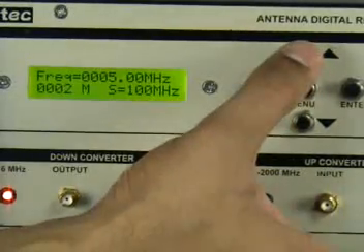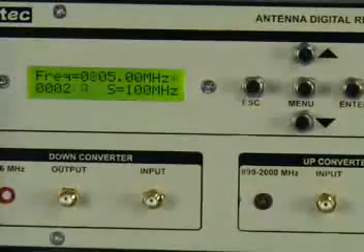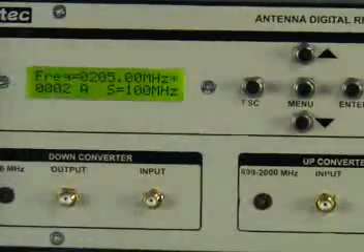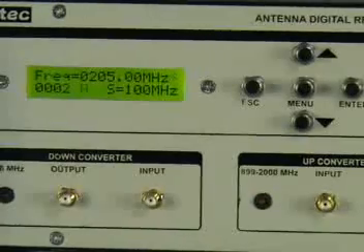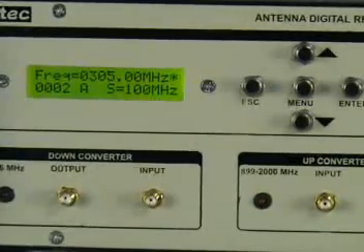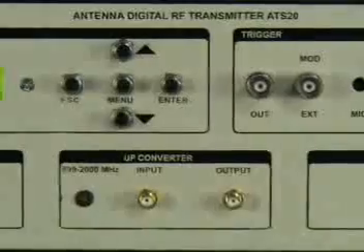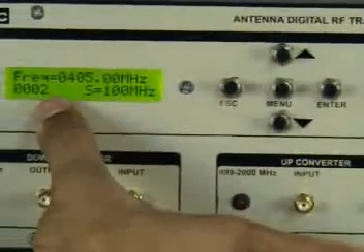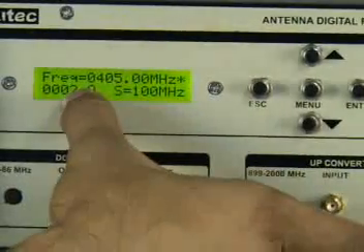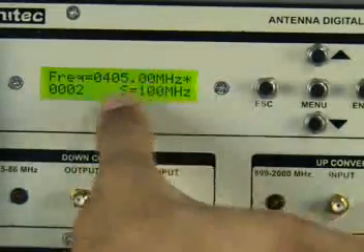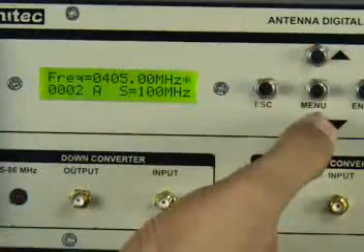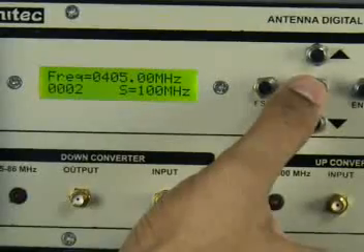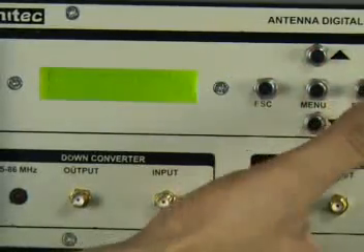Similarly, there is an auto mode. Now when we select the auto mode, as you can see, the step size selected was 100 MHz, which is again displayed. So the frequency is changing in steps of 100 MHz, and the triggered output is available at out. When the display is glowing or blinking, we cannot change the frequency normally. So always ensure that while operating the system, this has to be in M or manual mode.